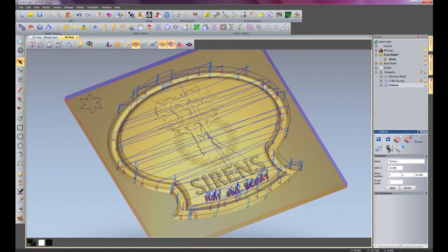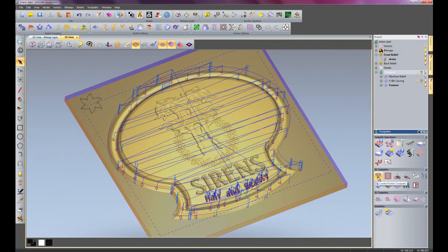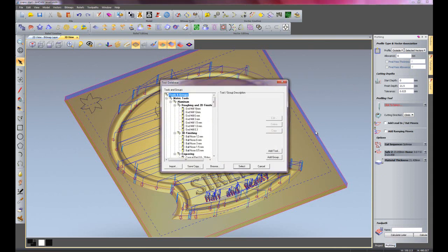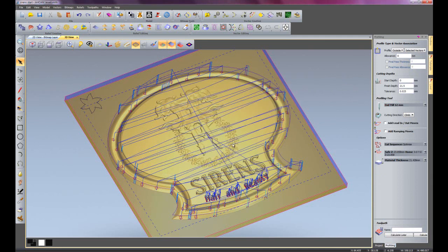and I'm going to go on to my next toolpath, which is just basically to cut the part out. So I'll select the outside profile, go into toolpaths and create a profile toolpath. The finish depth, just going to do that just a little bit thicker just to make sure that it goes right the way through the material. And the profiling tool, I think I'll use the same 12mm end mill that I used previously and then click calculate. So that's created the cutout for me.